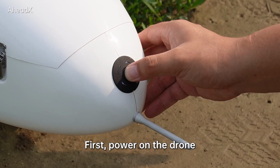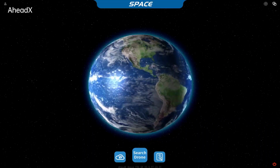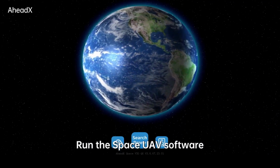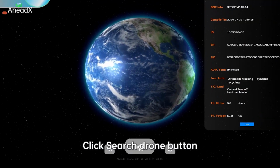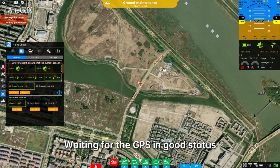First, power on the drone. Connect the data link to laptop through USB cable. Run the Space UAV software. Click Search Drone button. Enter the main interface, waiting for the GPS in good status.